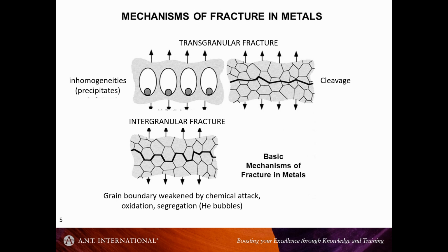Just to summarize, we have this mechanism, typically how a material might form a crack, even without a crack, to create a stress intensity if the material is hardened and the stresses have built up sufficiently and the plastic deformation is sufficiently high that there is a large incompatibility between the matrix and the precipitates.